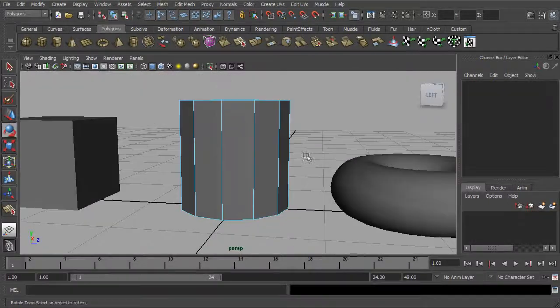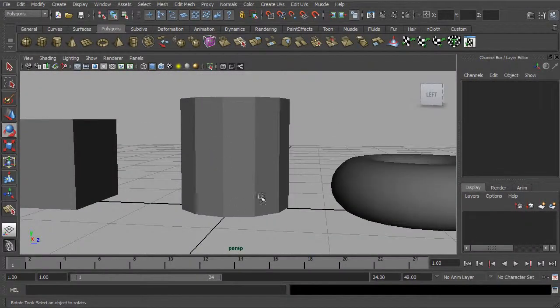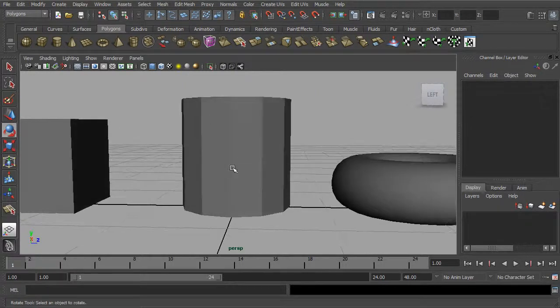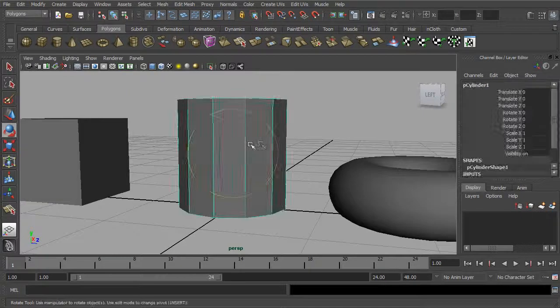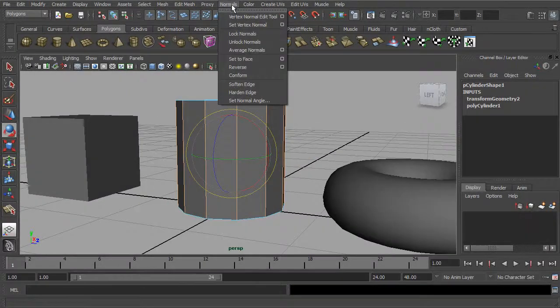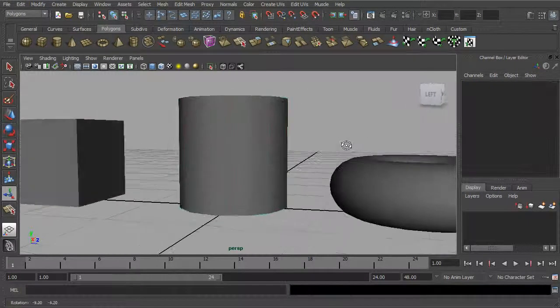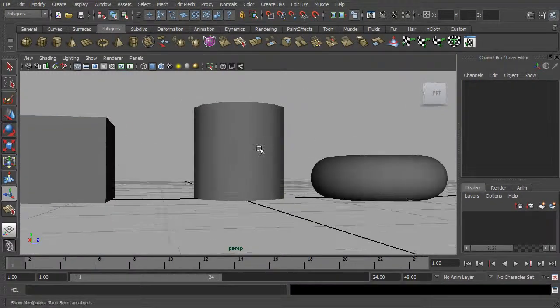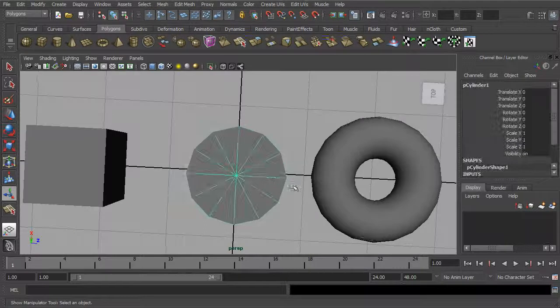And right now, they're kind of hardened. So each one of these faces you can see gets distinct shading, and there's a nice distinct line between those. Okay, so if I were to go ahead and take the edges, go to normals, and soften those normals, you can see from the side it actually looks fairly smooth because it's blending that shading between those different edges, even though we haven't added any resolution at all.